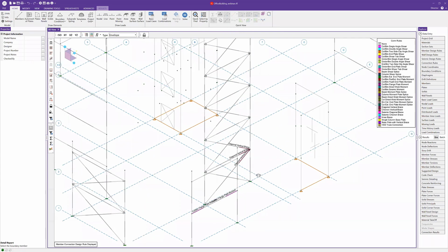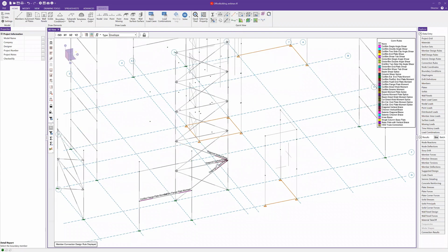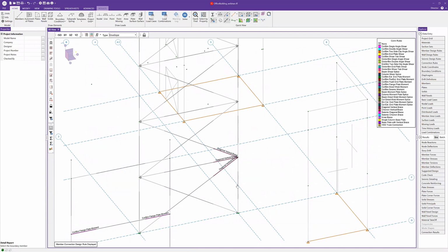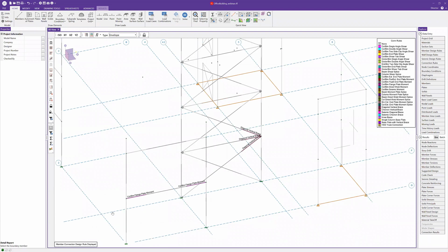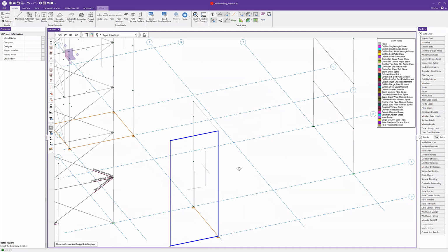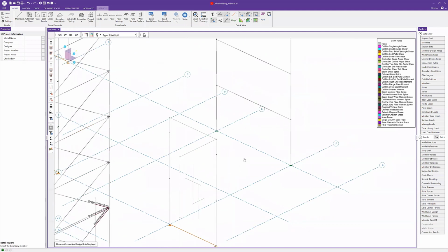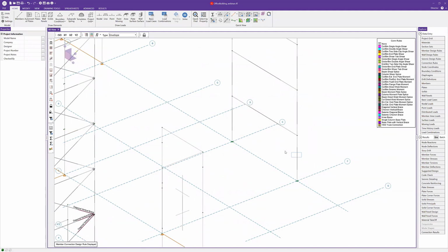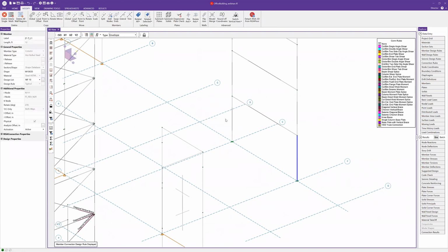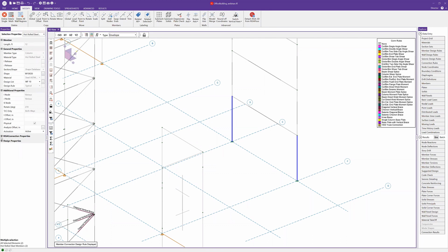In this particular model, we have a diagonal vertical brace, right? So I have wide flange with angled braces. We also have a column beam, flange plate moment connection. Maybe I want to assign something else. So I'm going to come back here and say, let's say at this column and this column, we're going to assign RISAConnection properties here in the properties panel. And we'll say that at the start of both of these, we're going to do a single column base plate.